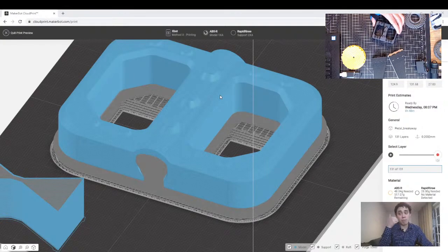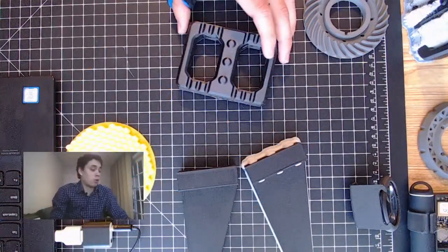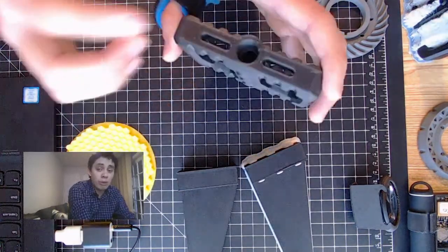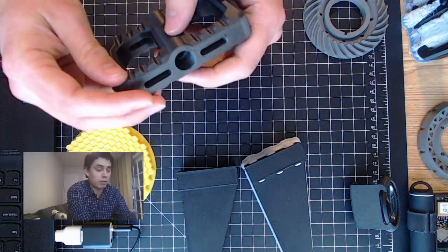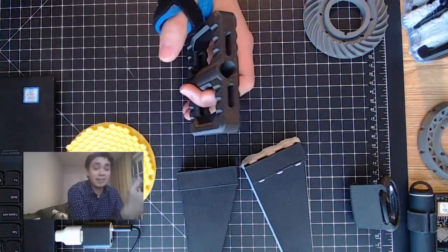Again, to recap: consideration one, is this part going to withstand a force applied to it, and how is that force being applied? Consideration number two, how will this affect my material choices? How much difference does it make when I'm talking about the supports that I'll be using and the amount of support material, because it affects the time. And the final consideration, but I think it's also super important, is how will my part orientation affect the actual appearance of my part, right? Is that a consideration?